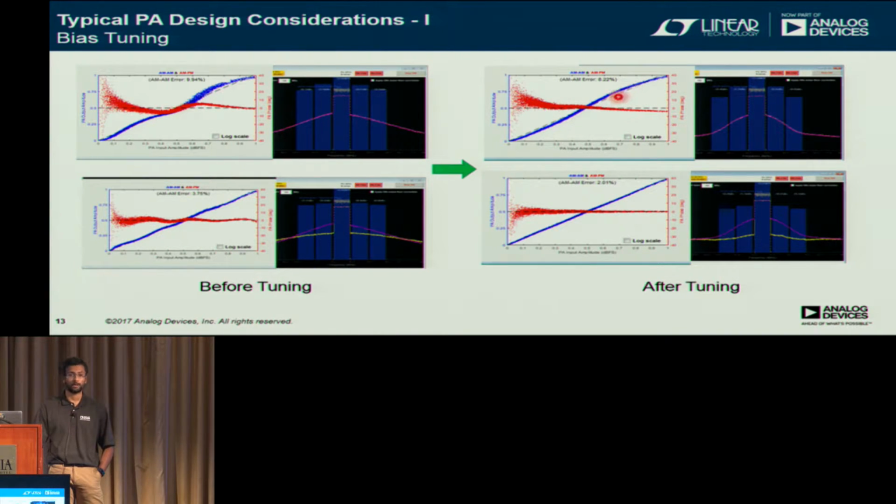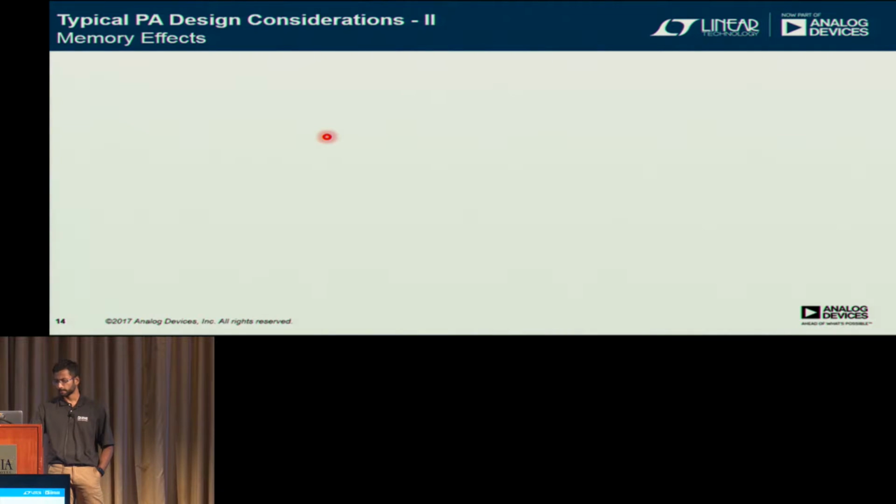But you can do a lot with just that. That's what I'm trying to show here. This is a lot more ideal. It's just a much more benign looking AM to AM and AM to PM curve, and that's way more linearizable than the previous case. So I took an efficiency hit on the PA, maybe 2 to 5%, but I end up being able to use maybe an integrated DPD solution that gives me an overall system benefit. We'll analyze that in a few more slides.